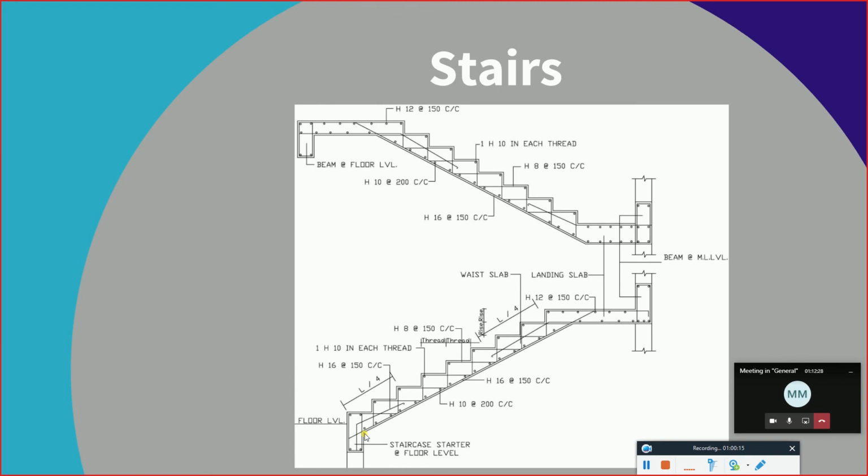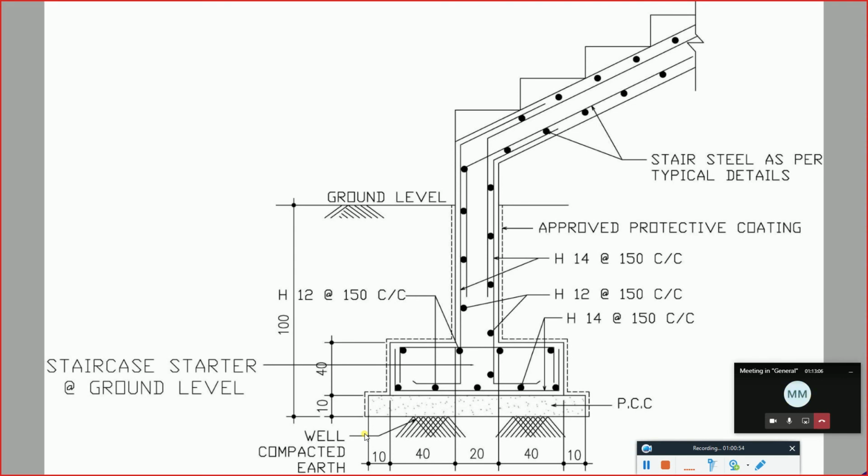Okay, so nobody is going to ask you how much it's going to be this length and how much is going to be this reinforcement, because that depends on the design itself. But you need to understand that based on this bending moment, this is the reinforcement, how it looks like, whether you are talking about a slab or a beam or a stair or a wall. So the major thing is the bending moment diagram, which will be repeated mostly in each and every interview, whether you are going to be asked about the detailing or whether you are going to be asked to draw the bending moment diagram for any scenario. Okay, and this is what we say for the foundation as well.